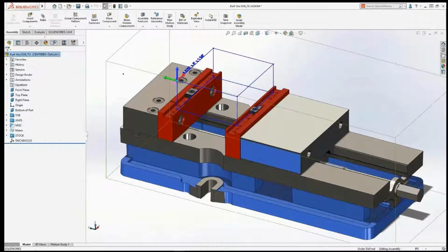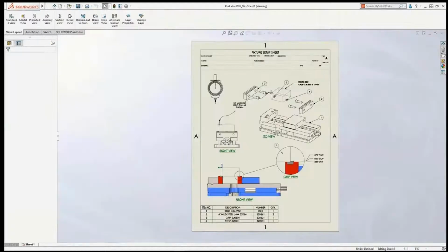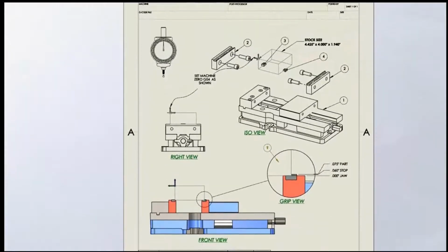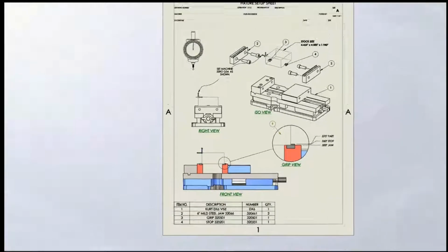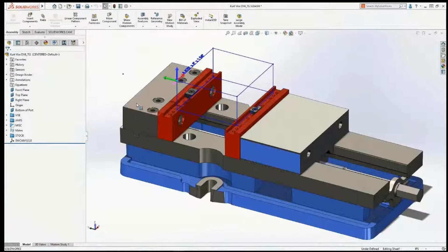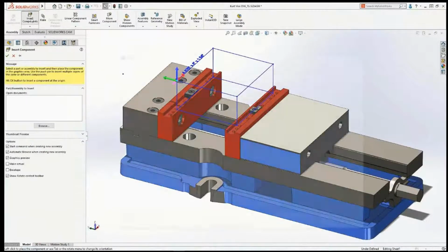I prepared a model of the device to mount the part, which we need to perform machining for. Using 2D drawing in SolidWorks to show more details for the device and how it could hold the workpiece, and setting up the zero location, the places for dial indicators and the gauges and so on.